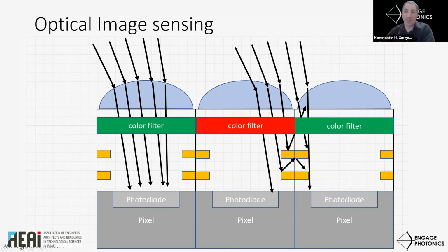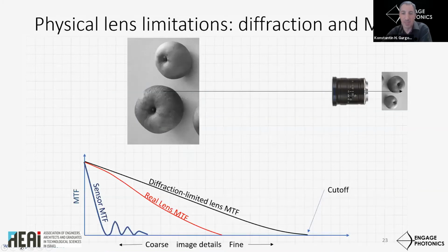Some image sensors are backside illuminated, meaning that the sensor chip faces the lens with the silicon side, and so there is less scattering and blocking. That kind of sensors have higher sensitivity and better SNR. If we calculate the transmission function of a discrete sample and hold function, we will get a sinc function.